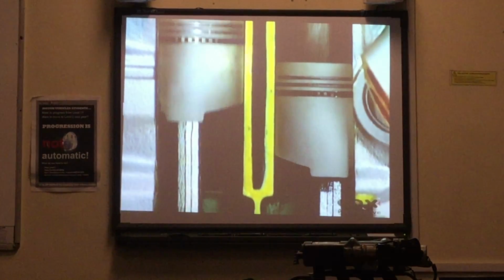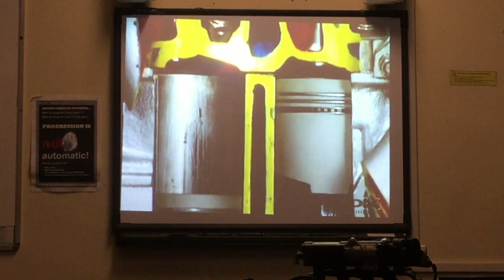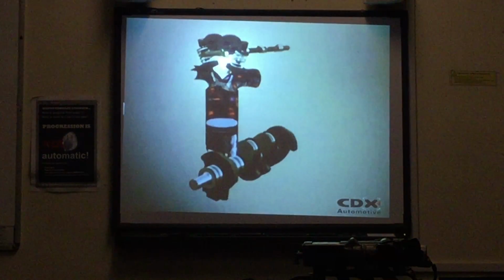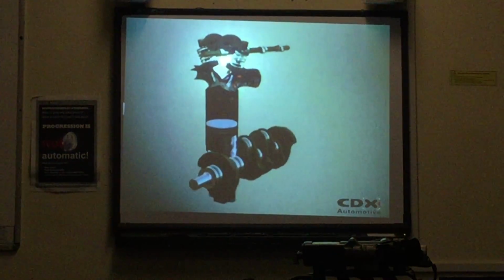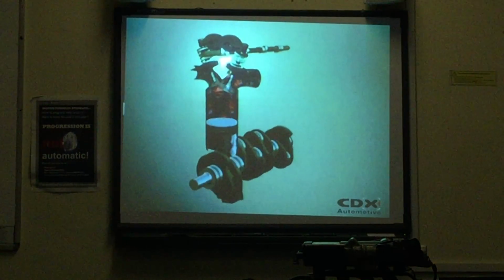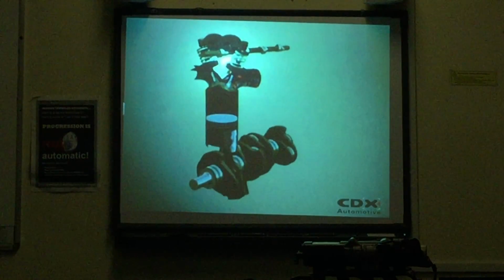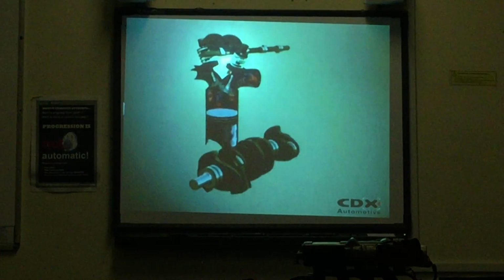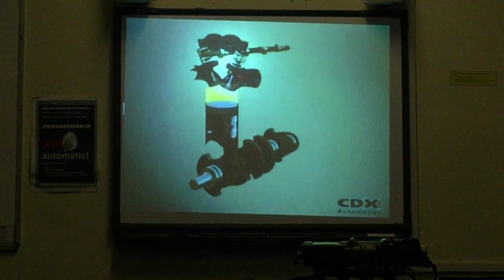These 5 events occur in all internal combustion engines. How they happen can change, but they are always there. In one 4-stroke cycle, the crankshaft does 2 revolutions. In those 2 revolutions, how many strokes does the piston make? It makes 4 strokes. Out of those 4 strokes, how many actually produce energy? In one 4-stroke cycle, only 1 stroke out of 4 delivers new energy to turn the crankshaft.